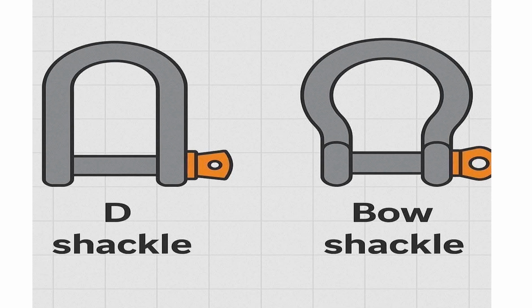Next, most of the time we cannot use the sling directly. We need D shackle and bow shackle. Currently, too many employees are confused about the two shackles. You see the D shackle comes with that D shape. Here it has the thread inside. The bolt also has the thread, the same pitch. Before you use this one, inspect for any bend, any wear, any tear, any thread damage. Check whether it is in good condition. Then we are going to use it.